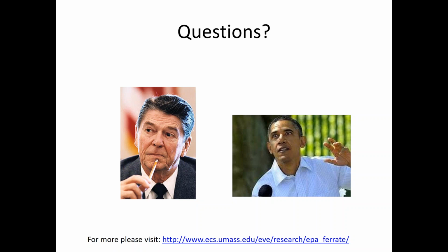The first one I'm going to read, you may have answered, this question may have come in before you provided an answer, but I'll read it anyway. The question, brought in by Brad, is: we use chlorine dioxide as a primary oxidant. Would ferrate be considered a replacement for chlorine dioxide, or would there be an advantage in using it in conjunction with chlorine dioxide? Well, my perspective is that it could be used as a replacement for chlorine dioxide.